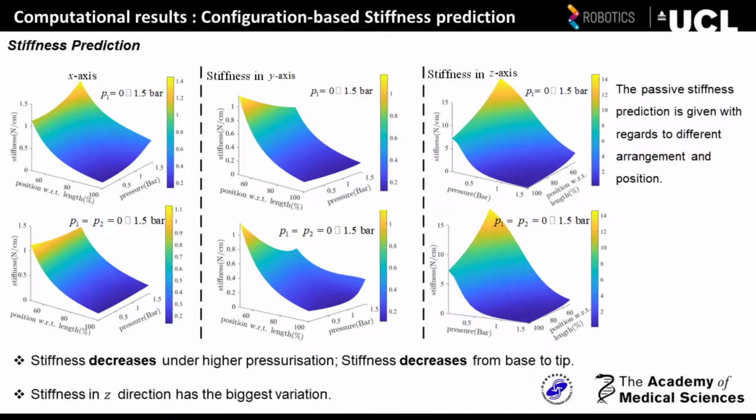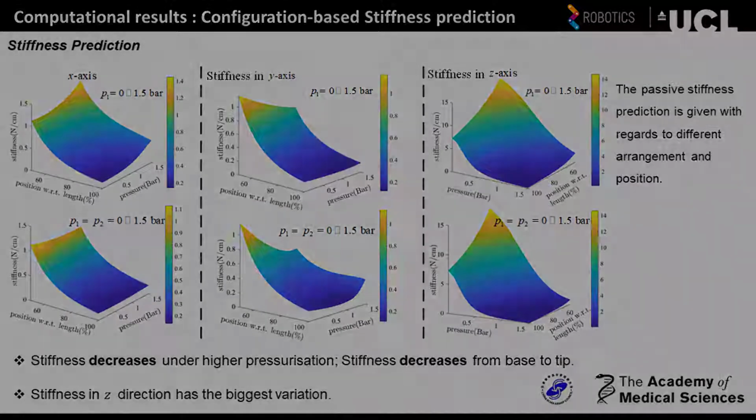The stiffness prediction along the robot and in different configurations is given. It is found the overall stiffness decreases with the increase of the pressure. However, in a specific direction, the stiffness may increase. The stiffness also decreases along the manipulator, but in different directions, it has different responses. This prediction reveals the underlying stiffness property of the robot. Such results could be used to determine which direction of configuration would have high stiffness in order to achieve on-demand stiffness analysis and improve the stiffness capability of soft robots.